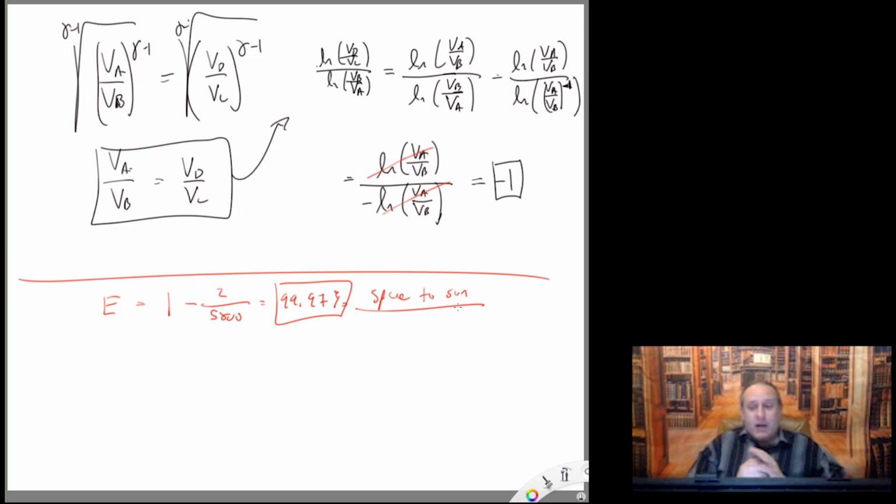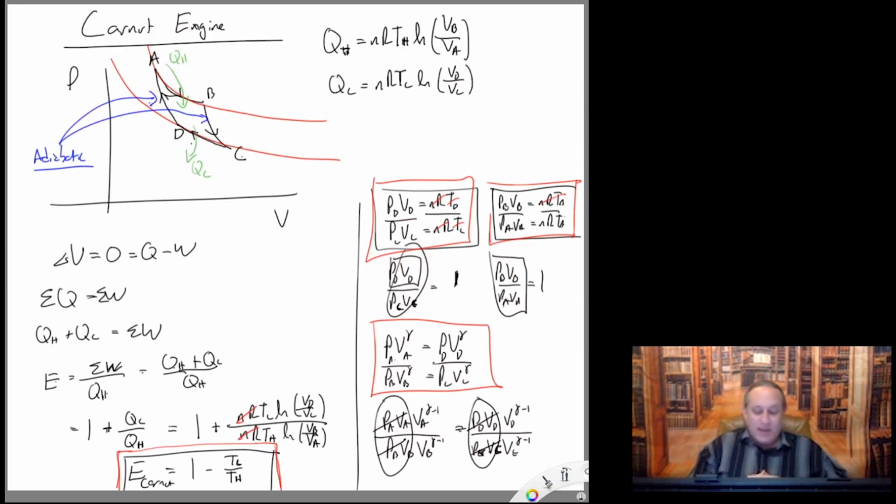All right, so that's how the Carnot engine works. When we're solving problems, as a last step, sometimes we're asked, how does the efficiency of this machine compare to the maximum theoretical efficiency? And that just means, what's the Carnot efficiency between the hottest temperature in that problem and the coldest temperature in that problem. Once we find those temperatures, we can easily find the Carnot efficiency.